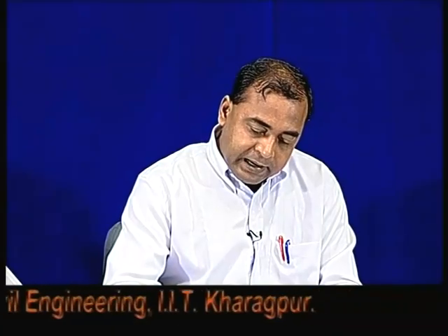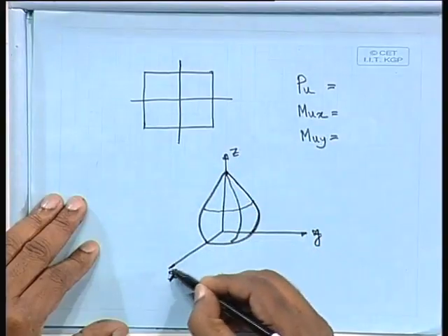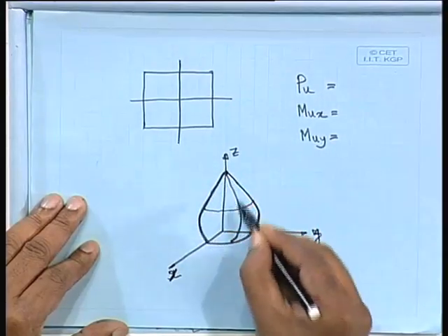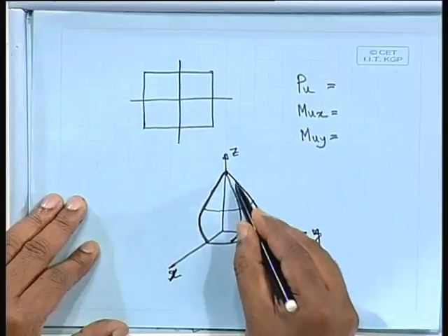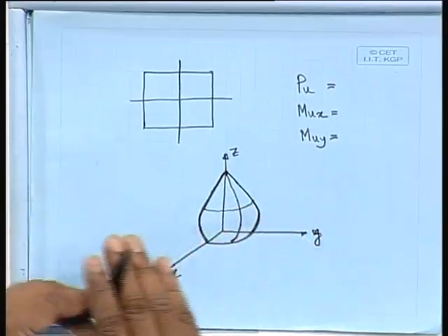What I am trying to say, the curve you are having along this axis, that means y and z axis. So, we are having this one interaction curve. Similarly, z and x axis, that is also another curve. In another axis somewhere I can get another one. So, like that I can make so many interaction curves. Consider this as if you are taking 1/4 of an onion, as simple as that. If you take that onion 1/4 and cut it vertically, the shape which you will get is the interaction curve or interaction diagram in 3 dimensions.